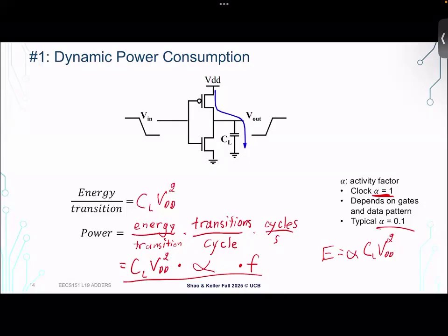Yeah, in these analyses, we roll all the capacitances, parasitic and wire, if you like, into this total CL, because for the purposes of energy, we don't care what capacitance we're charging. We just care how much in total we are.